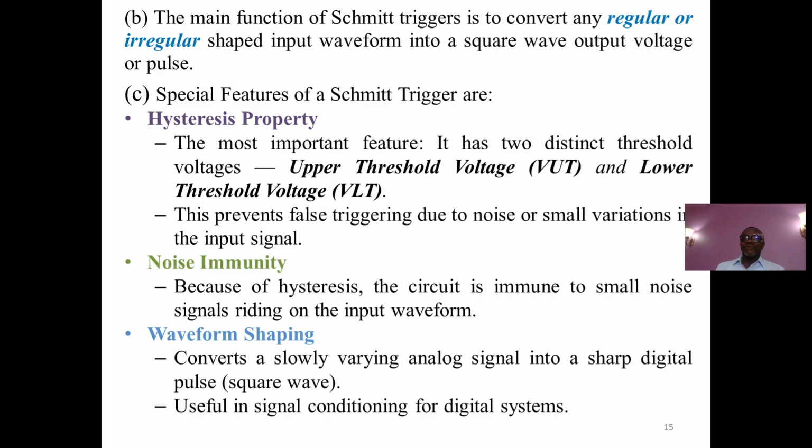But the voice signal coming from my voice is very irregular. It may be sometimes peak high and sometimes low. So immediately we establish what is known as the upper threshold and the lower threshold. Anytime my voice signal crosses the threshold up, it becomes the leading edge. Anytime it crosses the lower threshold, it becomes the lower edge of that conversion from my voice.